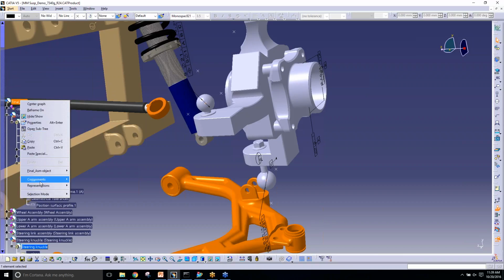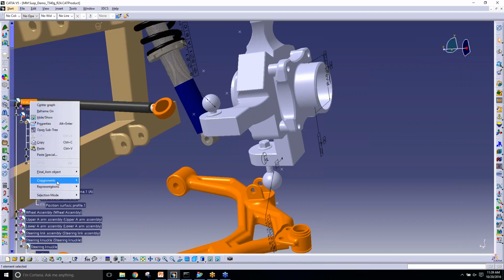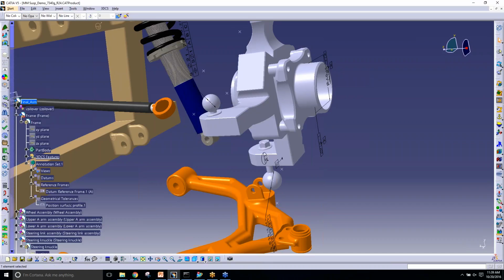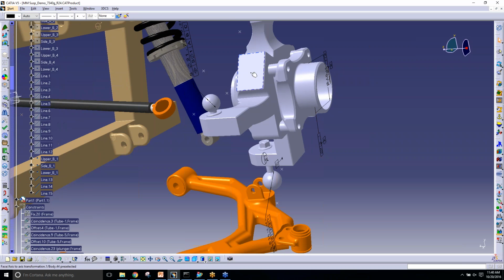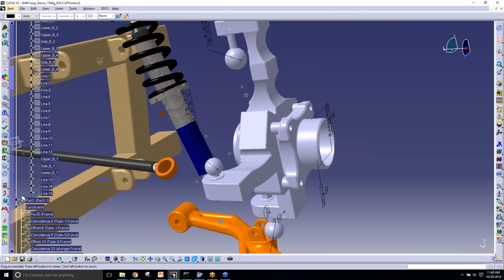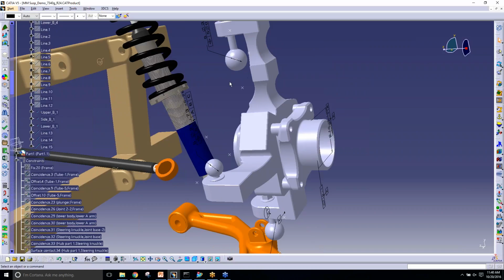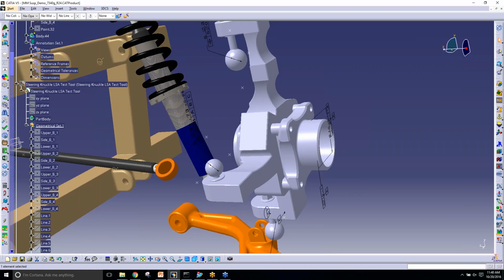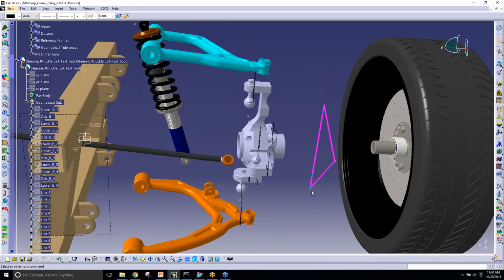So I can just insert a new component, or new part, and I can copy those new points right into that part, and that would be based on the XYZ position of the knuckle. Then basically from that fixture, I can just translate it out like I did with the steering knuckle fixture here, and there's my fixture, with all the same 3 points.